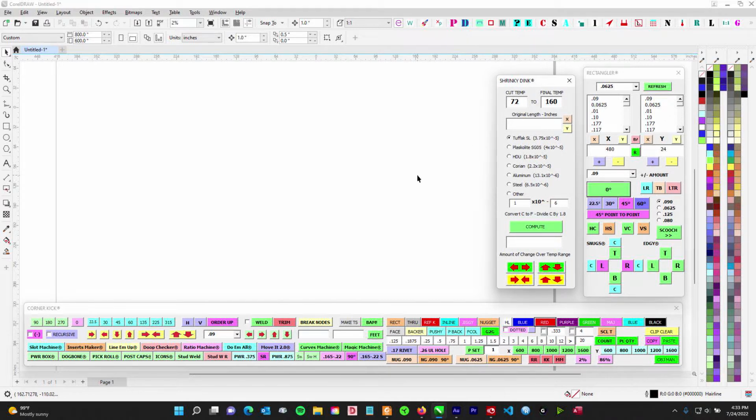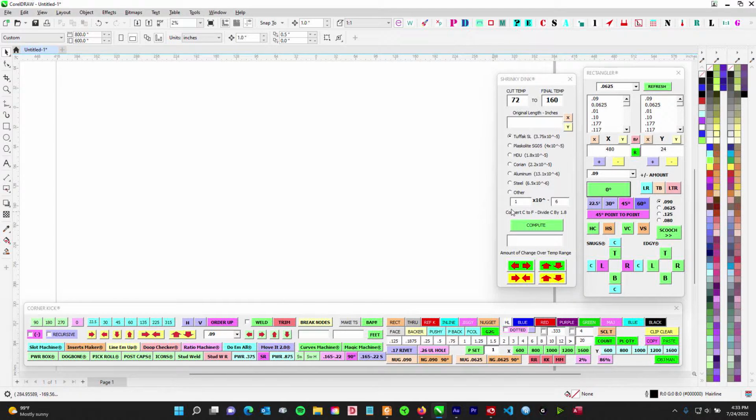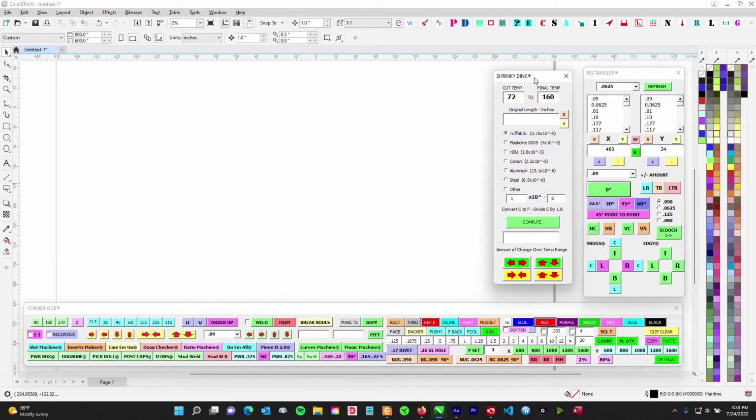We had a particular job go sideways, and it was because we didn't understand the basic mathematics of this kind of stuff. So what I'm going to do is show you how to find this information. I'm also going to show you how to use the macro, but in showing you this, I'll show you how you can figure this stuff out on your own, with examples of how powerful this is in our industry, stuff that goes wrong and goes right with fabrication. As a designer, when you're laying stuff out, you think, I'm going to use these different materials and mix and match them. Well, you better be ready for the fact that some of them want to grow more than the others, or they shrink more than others. And that's where we get into a lot of trouble.